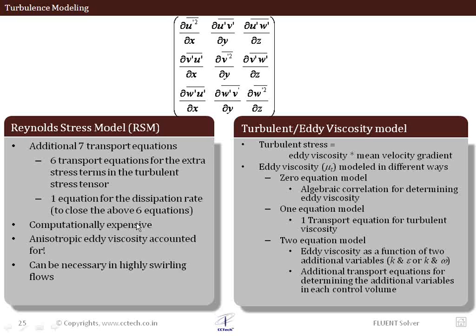It is computationally very challenging, and it does account for the anisotropic eddy viscosity. So it does not assume constant eddy viscosity, so there is no problem which we encounter in this eddy viscosity approach, which I'll discuss just in a minute. And it is very helpful for predicting the turbulence phenomena in highly swirling flows.